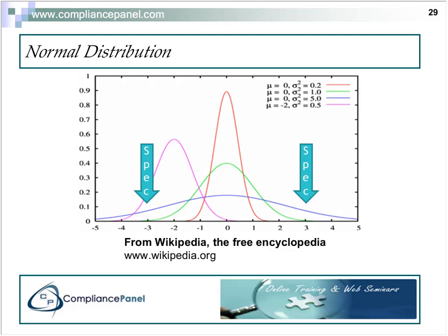Now, of the specification, 0 is the ideal location, and we have in this case a plus and minus specification that's equal. Not always the case, but in this case it is. And what we've done over time is we've adjusted the distribution of this process. Originally, we might have been in the blue distribution, which ended up producing product outside our specifications, and therefore we're producing some good product, but we've got to sort through some inspection process to find the good product and then to either scrap or rework the product that falls outside spec.